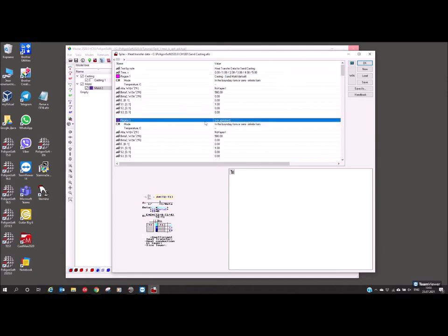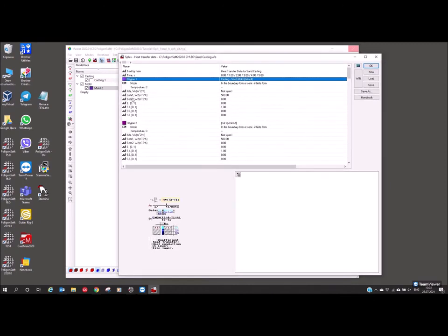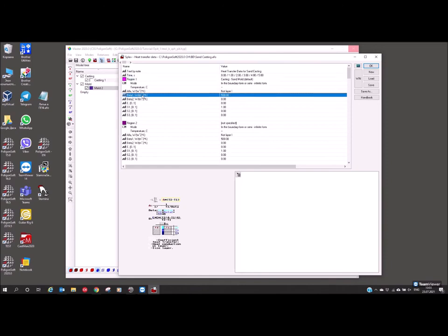But every region is some part of a boundary, and for this boundary we can specify some heat transfer conditions. If its boundary is inside, if it is an interface between casting and mold, we can set here heat transfer, for example, beta 1, and the beta 2 is the same heat transfer, but we can use it for convection, for example.